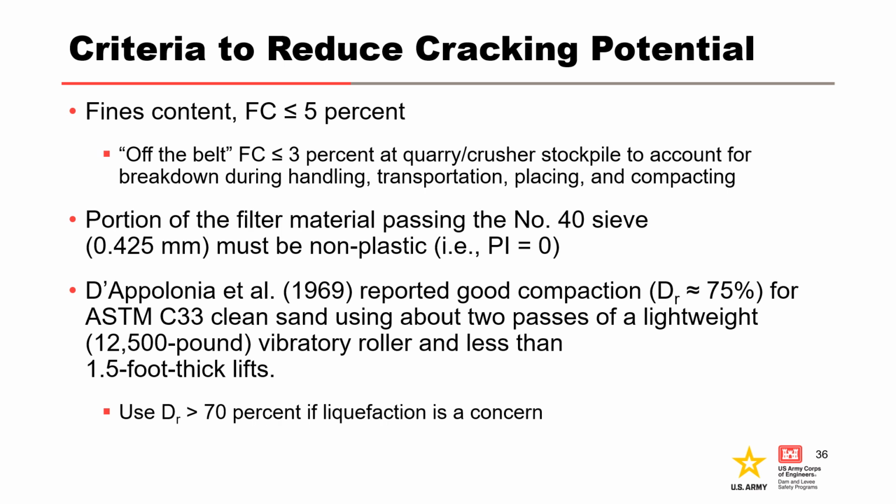Compaction of filter and drain materials should be adequate to produce sufficient density to preclude liquefaction, limit consolidation, and provide adequate strength. Minimum density should generally not be less than 70% relative density, particularly if liquefaction is a concern.